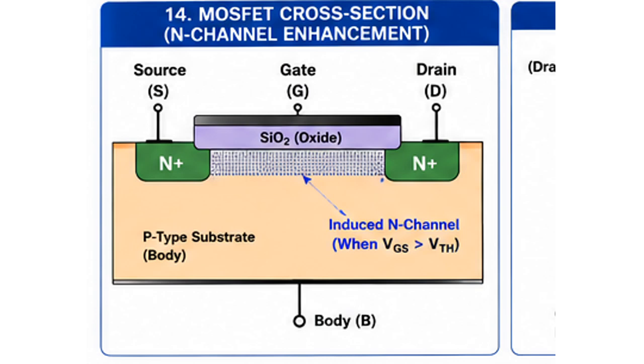Many beginners become confused about polarity because they think only in terms of voltages relative to ground. The important quantity is always the gate-to-source voltage, VGS. Consider a P-channel MOSFET whose source is tied to plus 12 volts. If the gate is driven to plus 5 volts, then VGS equals 5 minus 12, which is minus 7 volts. That negative voltage is exactly what is needed to turn the P-channel device on.